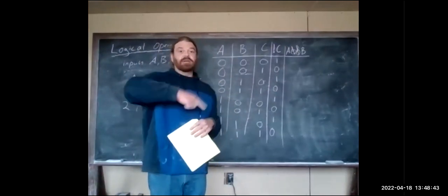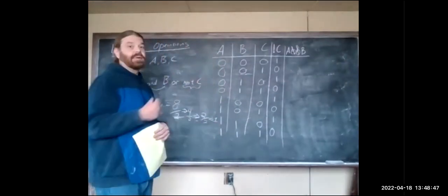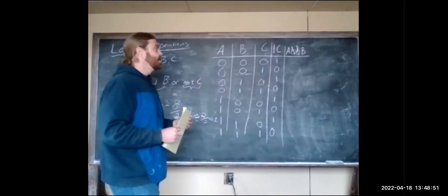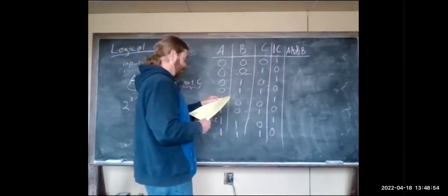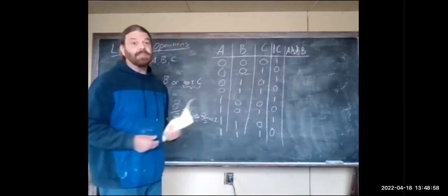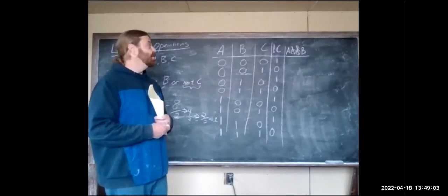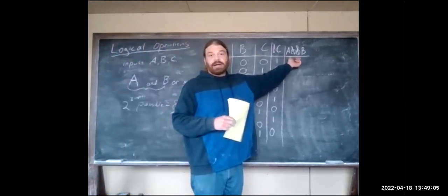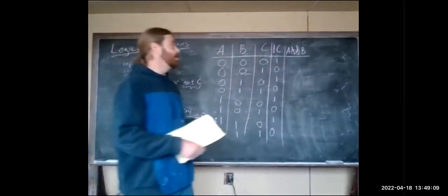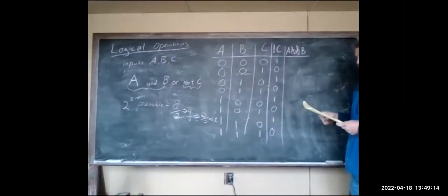It would go every single bit between the 2 numbers and give us what each column had in common as far as the and. The same thing with bitwise OR. We can do it bit by bit, and if we feed in 8-bit numbers, we get out an 8-bit result. Versus the 2 ampersands is our regular and, where if we feed in 2 8-bit numbers, we still get a 1-bit result. Usually this is the one we want to work with.